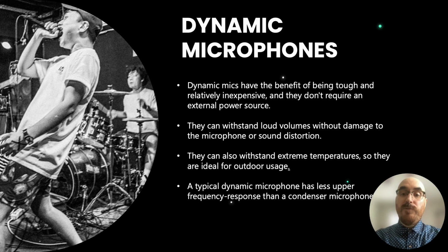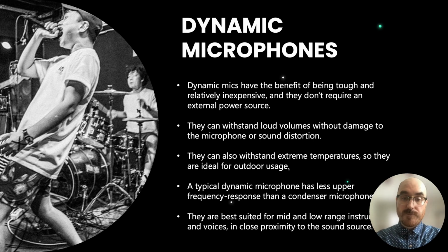A dynamic microphone usually has less upper frequency than a condenser microphone. They'd be great for recording something like trombone or tuba. Maybe not so great for recording violin, right? So that's the good thing about dynamic microphones. They're really durable. They do well with loud sounds, percussion, brass, voice, pop voice. They're good at rejecting sound from not right in front of them. So this is why they're the archetypical live sound microphone.